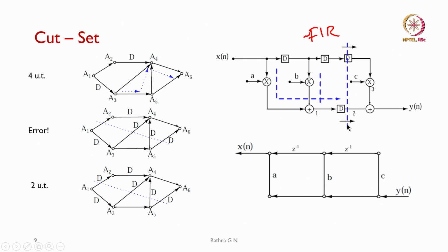The disadvantage is that we will be adding hardware to this structure, and the first output is going to be delayed by 1 clock cycle in this case, and later on we will be getting an output every T multiply plus T add from this structure. So, we said, can we avoid this cut set by modifying our structure itself.